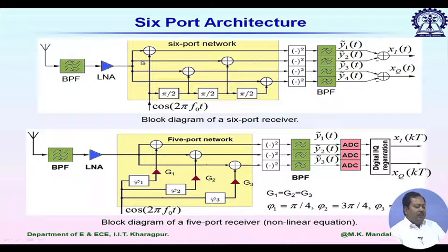And for the second, it is now being phase shifted by pi by 2, and it is added for the third line. Again it is shifted by pi by 2, it is being added in the second line. So, similarly for the fourth line we have 270-degree phase shift.